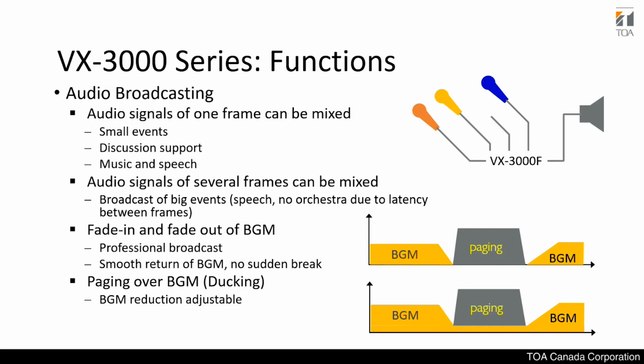You can route any input to any of the outputs of the VX3000 on any frame connected to the system. You can start with small events for, say, discussion support and music and speech reinforcements for local applications, or if you have a big location, you can broadcast and distribute it to your warehouse across multiple buildings and facilities. Although this is not advisable for a live event application because of the higher than acceptable latency. The latency for this is between 10 milliseconds to 20 milliseconds, depending on your network connection. So that's one consideration.